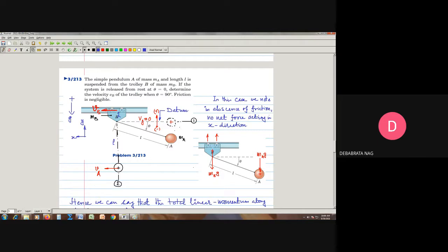But again, students, I would like to mention that it is to be remembered very carefully that whatever velocity terms we are going to use in these two principles, I mean the principle of work and energy and the principle of impulse and momentum equivalence, whatever velocities we use in these two methods or equations, they have to be absolute velocities, or the velocities as recorded from an inertial reference frame.